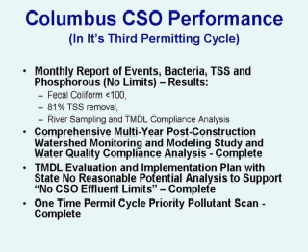The transmissivity after filtration was in the low 30% range. What we found was that we would have to run the contact over the bulbs at about 2 seconds contact in order to achieve the disinfection. Hydraulically, the filter and UV facilities were designed for about 24 mgd. Ultimately, we rated that facility at about 15 mgd, mainly to achieve the disinfection using a 2-second contact time.